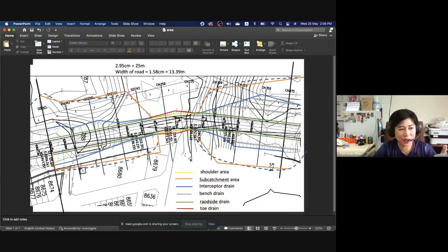So therefore you have all these tadpole symbols. For example, along chainage 275 to chainage 375, you have cut side slopes on the left and right. When I'm moving from smaller chainage to larger chainage, my left is the one which has more than 12-meter cut.